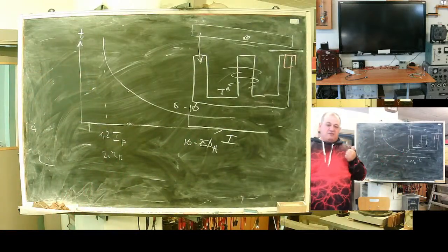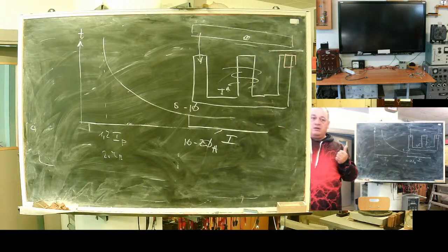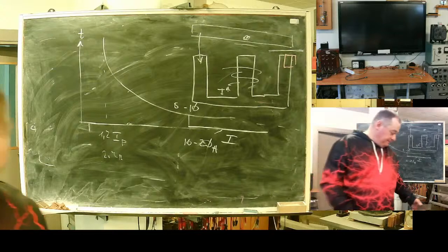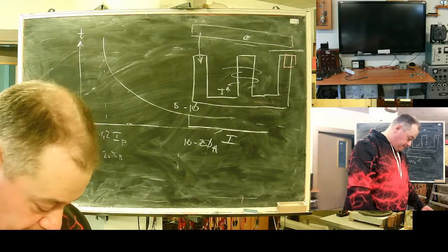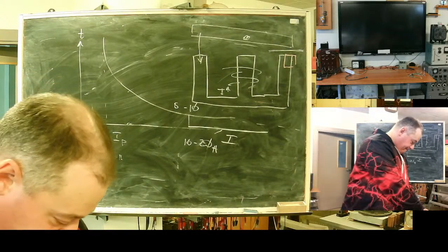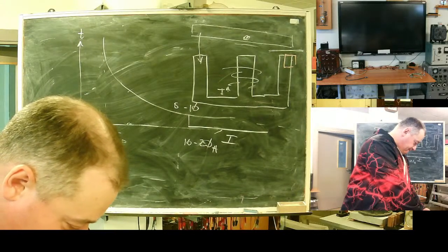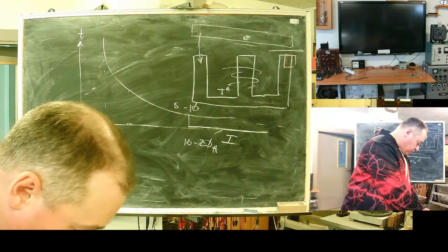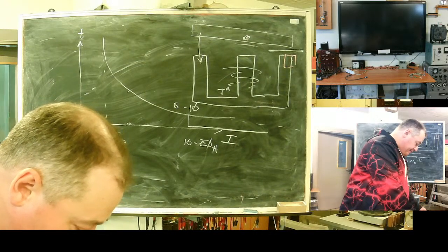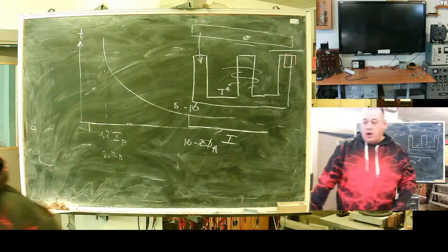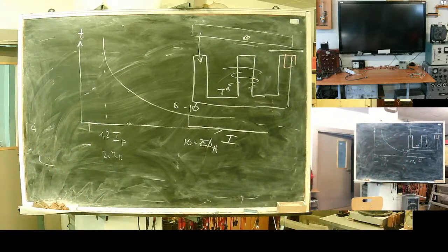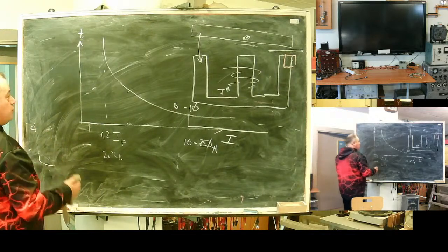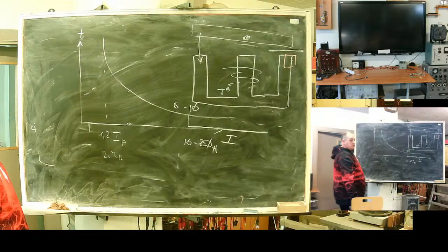What do we see in front of us? Actually, it's a base for 2 zones protection, where one zone is instant for line faults and another one works as time dependent, or you can use it as protection for your asynchronous machine.